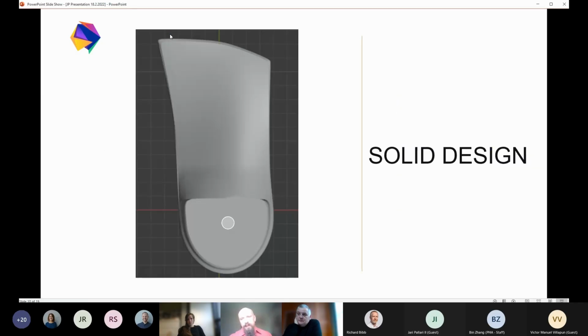And here's a little example of how you would define these features. This is a foot orthotic shell with a heel structure, and here we have a center of heel marker, and we also have the X and Y axis. So here I could define my heel: I'm going to take the distance between the back of the heel and the central heel marker, and then take a certain percentage of that, and go towards the distal edge, and that's where I'm going to draw the front of that heel post line.